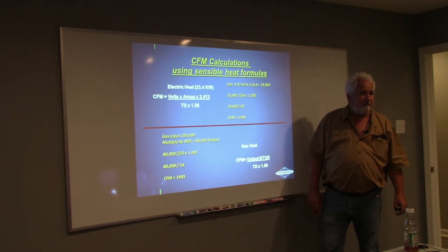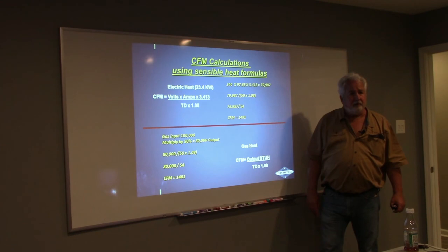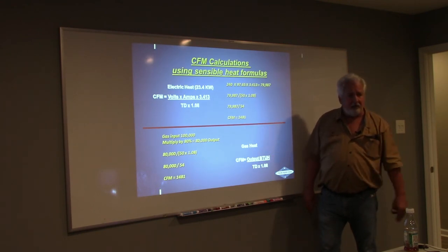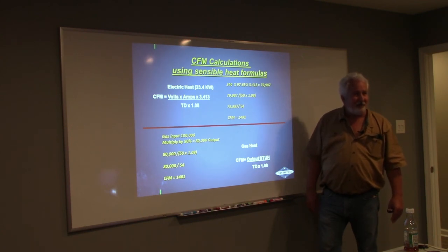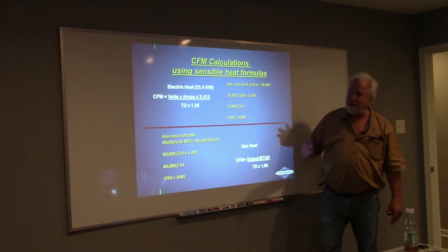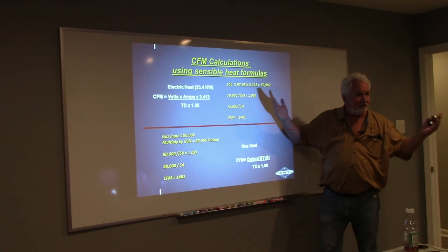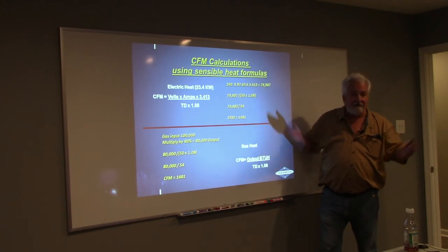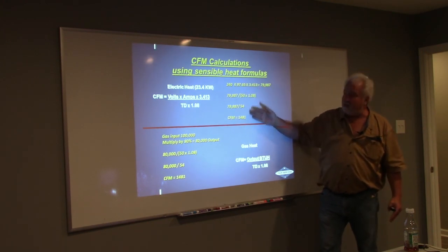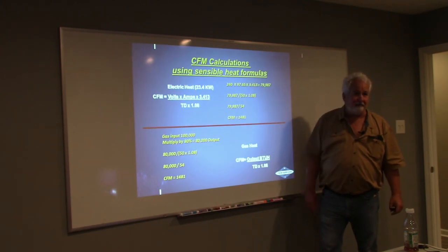So just by taking a few calculations while y'all are doing a heating maintenance, you can find out what the CFM is. If I'm doing a heating maintenance, that means it's wintertime. When do you want to change out ductwork, winter or summer? So every winter, if we are doing a heating maintenance, you're already checking the volts and the amps. You're already taking the temperature rise on the supply and return. I've given you everything you need to find out what the CFM is.